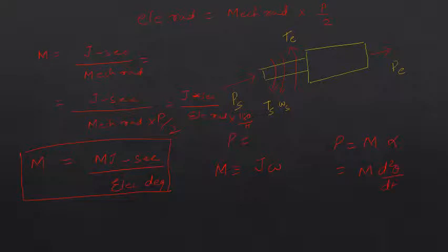Okay, now here this is the major relation you need to know about your power system stability. I know it is somewhat complicated, but you might have got a clear idea of what is happening with the mechanical system. I have not expressed it on the electrical side yet; I have just expressed all those things on the mechanical side, right? So here M is your J into omega. I have expressed that J was analogous to mass, and M is analogous to angular momentum.